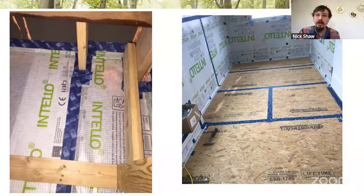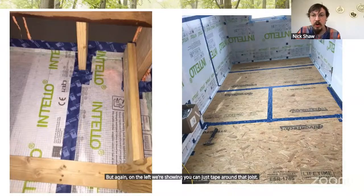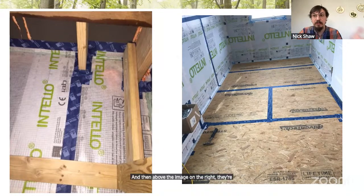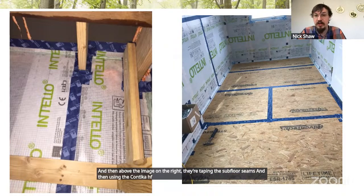But again, on the left, we're showing you can just tape around that joist. It's a little laborious, but it's nothing difficult. You can see that they're taping around that joist, and then they're taping to the underside of the subfloor. And then above, the image on the right, they're taping the subfloor seams and then using the Contiga HF to adhere the Intello to the top side of that subfloor, or using a Tescon Vana tape.